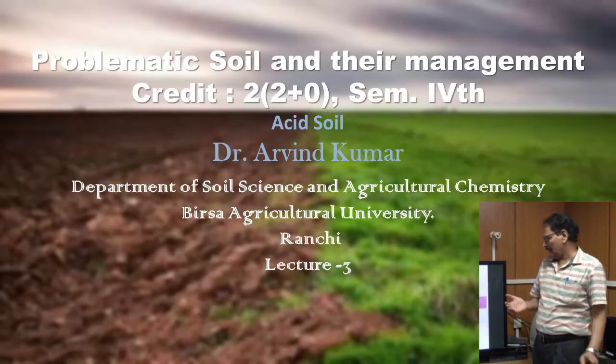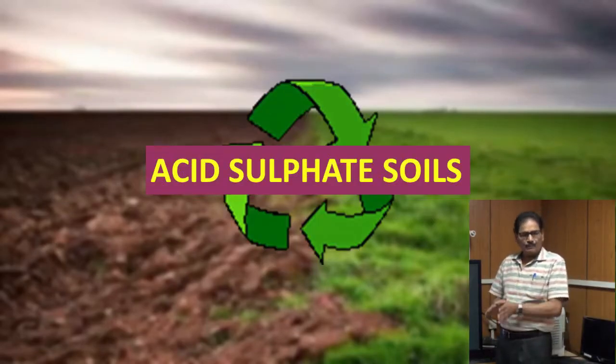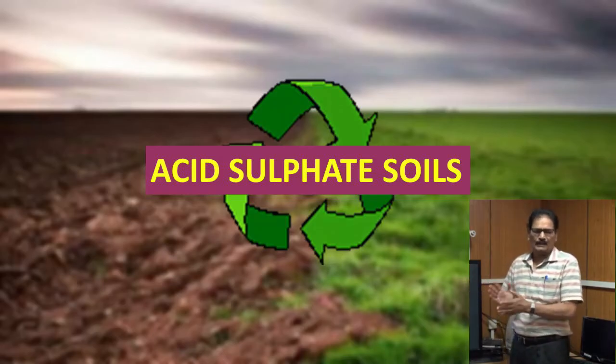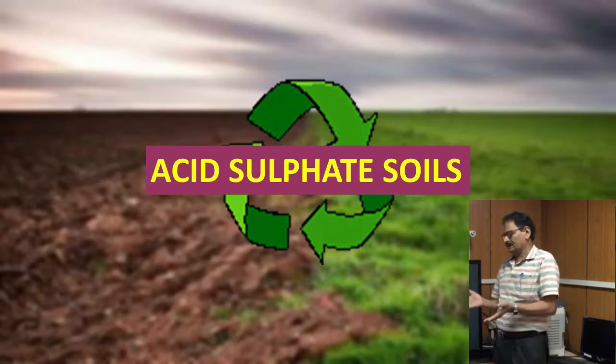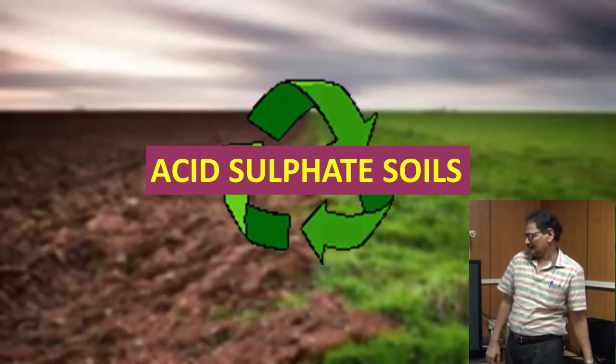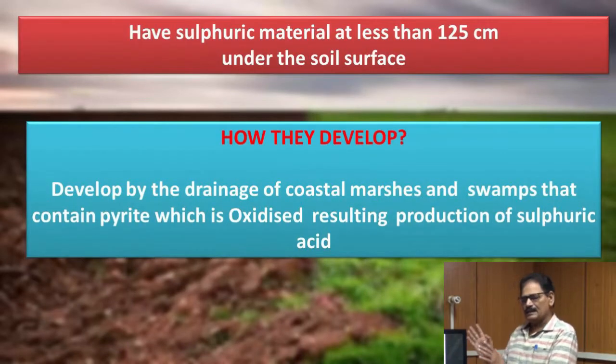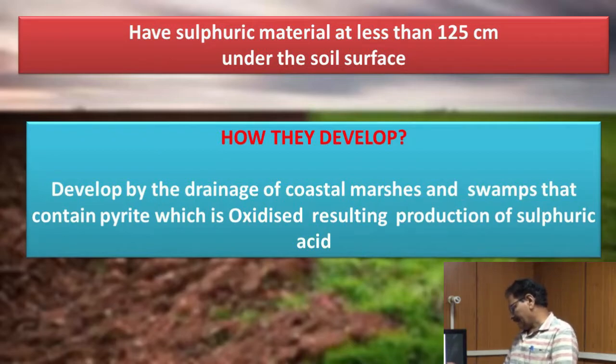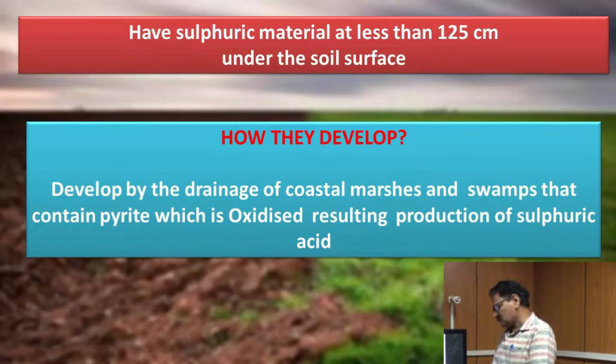Today I would like to start my lecture with a most important topic, called acid sulfate soil. This is a unique type of soil acidity, mainly developed in the coastal area, and mostly this type of soil is found in Kerala state. It is a soil formed by the oxidation of sulfur in the coastal area, developed by the drainage of coastal marshes and swamps that contain pyrite, which is oxidized, resulting in the production of sulfuric acid.